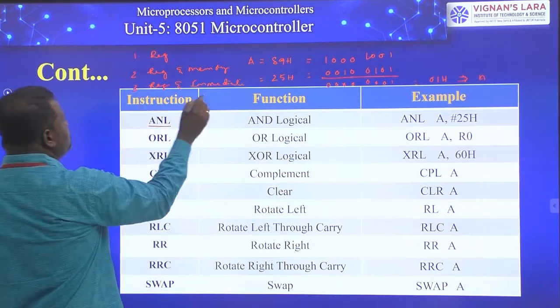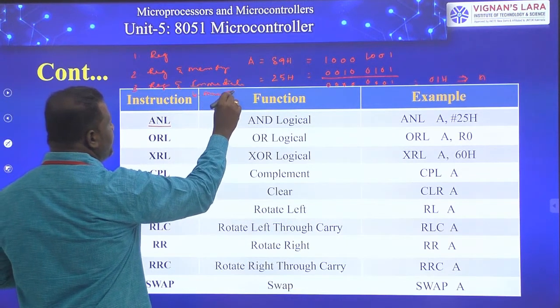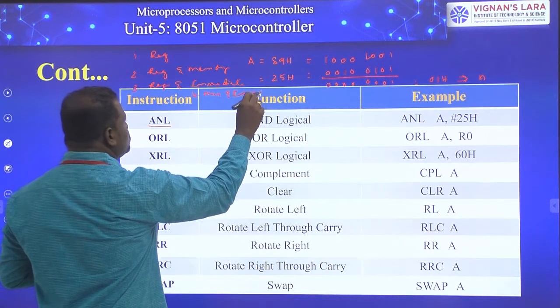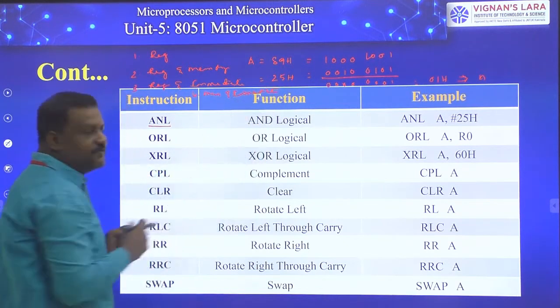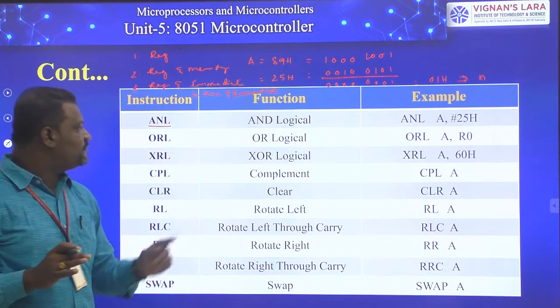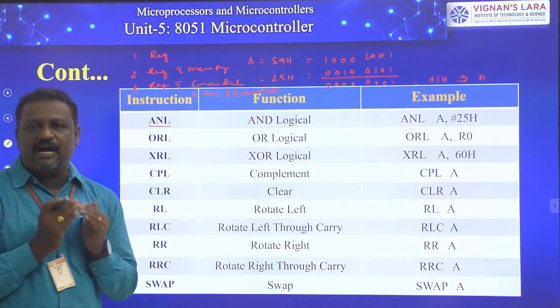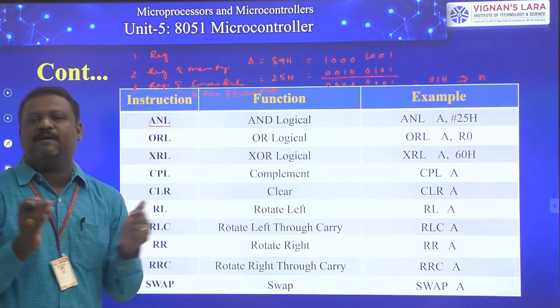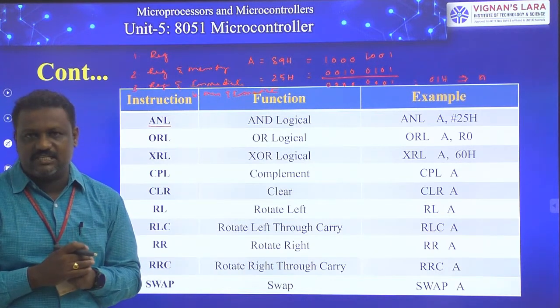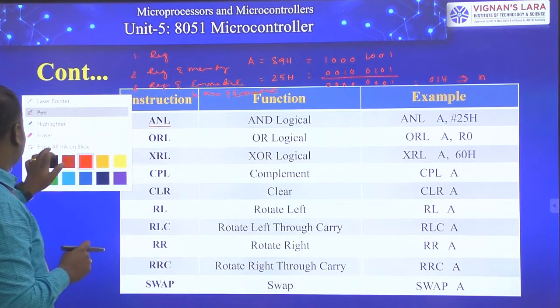And coming to the fourth one, it is a memory location and an immediate value. So these are 4 different varieties of operands you may identify in the operand fields of the instruction ANL. ANL means AND logical, bit by bit between the operands. That is the meaning of this particular instruction.